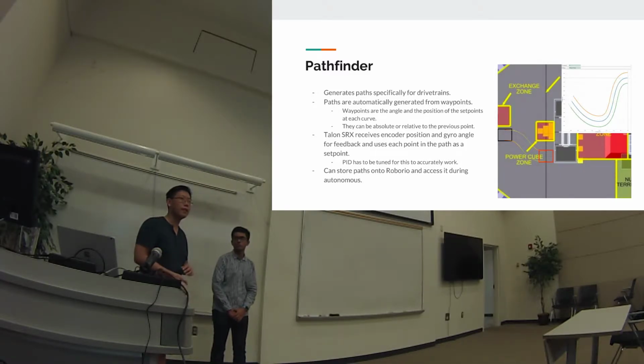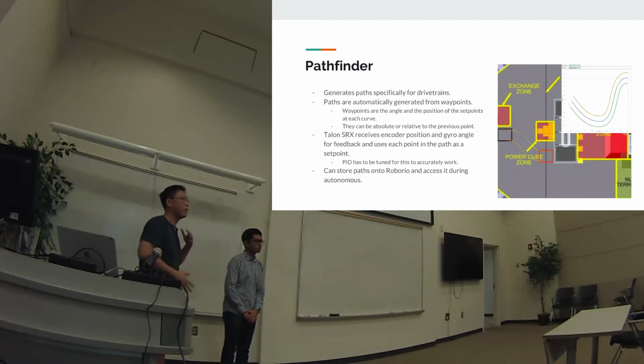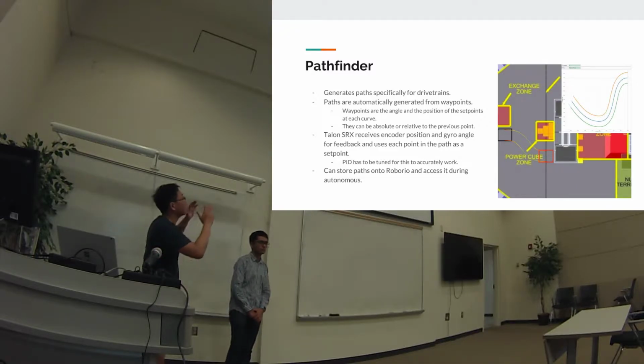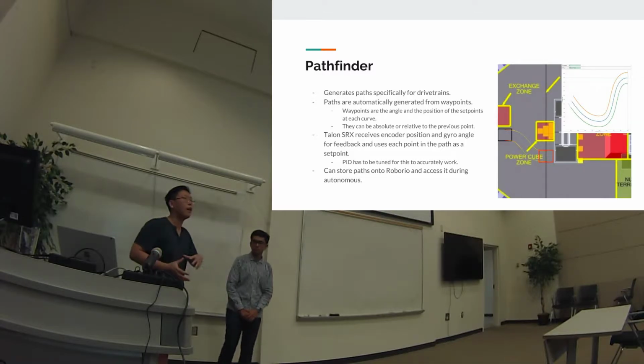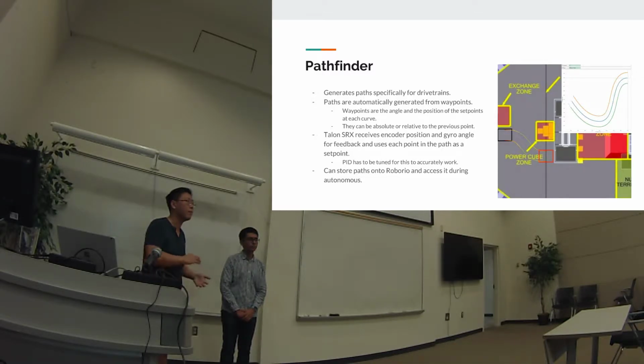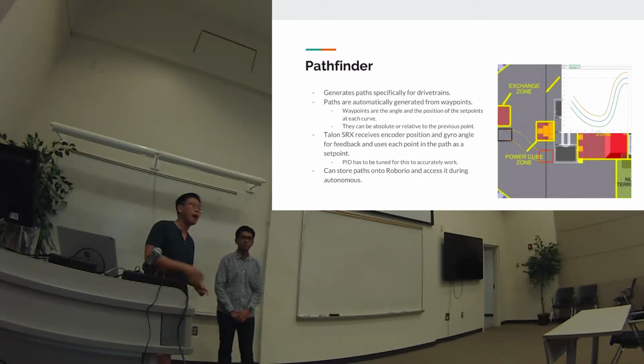We didn't find it as good when doing two-dimensional stuff like our drivetrain, just because there's so many tools available in terms of visualization for Pathfinder, and we literally see the field, we can plot where we want our robot to go, and then it'll generate basically a file that we can put on our RoboRio, and it can read that in. With the Talon SRX though, you have another control mode.